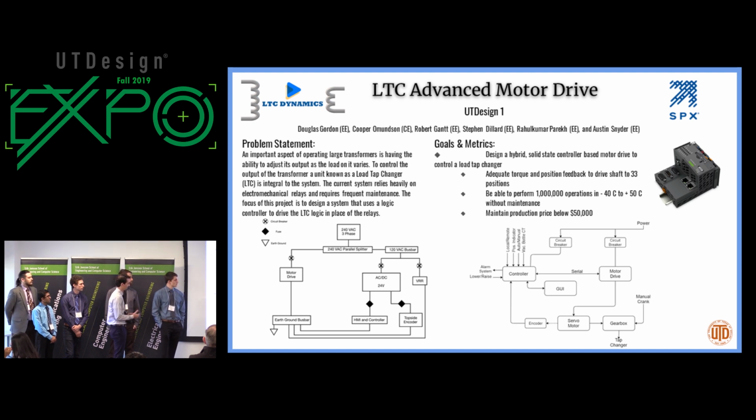So to start out, for a raise signal, the controller will receive a raise signal from voltage relays, and it will then, via an RS-232 serial connection to the motor drive, send a signal to the motor drive, which will then send a signal to the three-phase AC servo motor, which will rotate a shaft that will go up into the taps to raise or lower the taps.